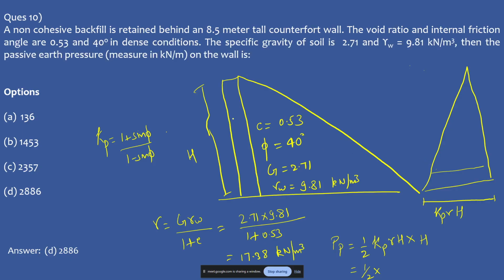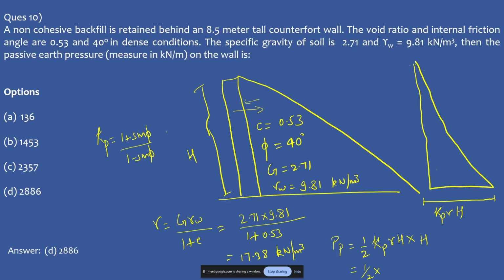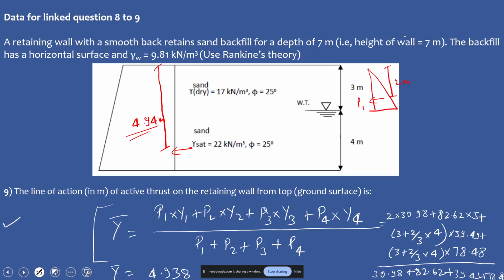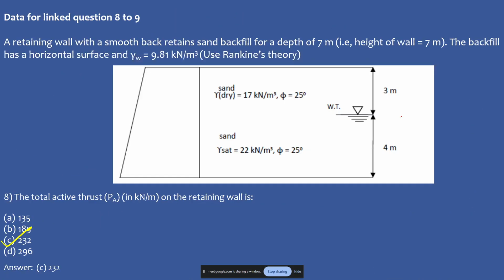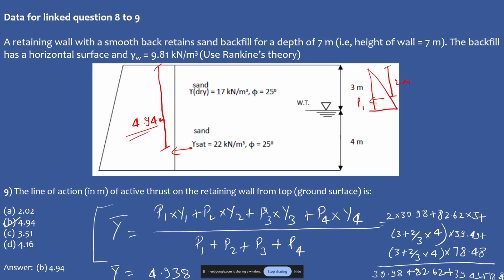Let's say I am having this retaining wall and this is my soil medium. If my retaining wall is moving towards the soil, the soil will provide the lateral earth pressure in this direction. Then the previous diagram is okay, that was correct. I think in that previous case I made a mistake. Only the formula will take care; the pressure diagram will be the same. The formula will take up Ka and Kp.